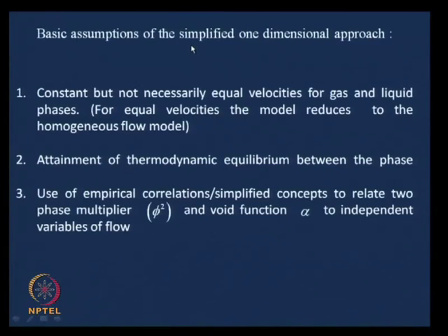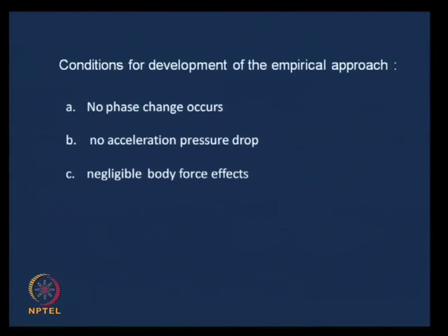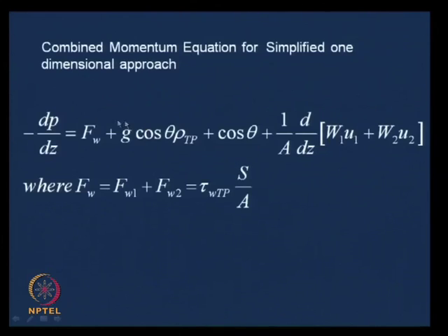correlations for finding the frictional pressure gradient as well as the void fraction, they were developed on the basis of no phase change, no acceleration pressure drop, and negligible body force, such that the total pressure gradient can be made equal to the frictional pressure gradient.